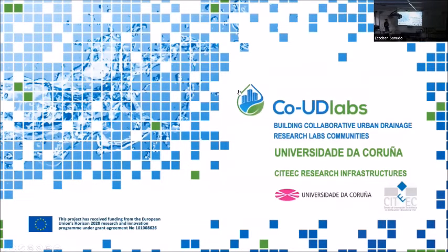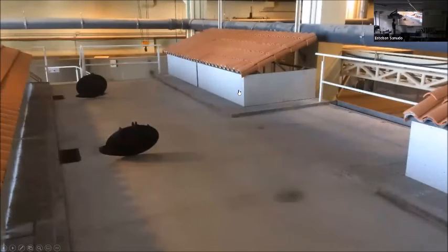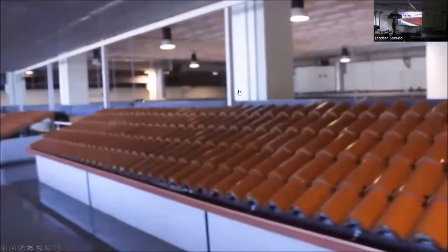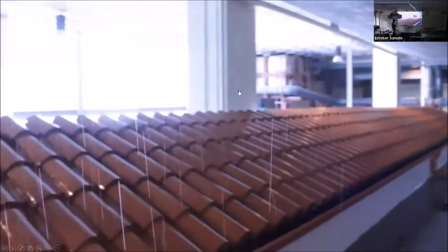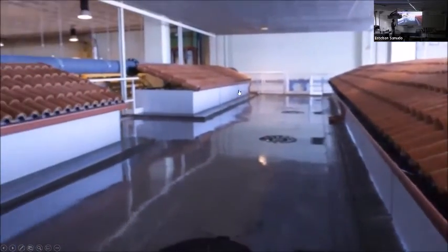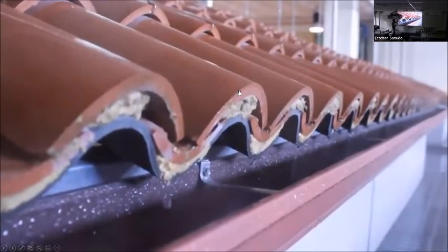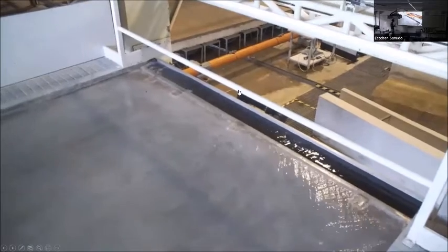This is a promotional video of the facility. All the things that I explained are collected in this video. This is the facility. This is the rainfall simulator working. As you can see, it's completely real rain. That's the roof with the gutters. And this is the runoff generator, with which we can put runoff on the surface to simulate the effect of an upstream street or upstream neighborhoods.